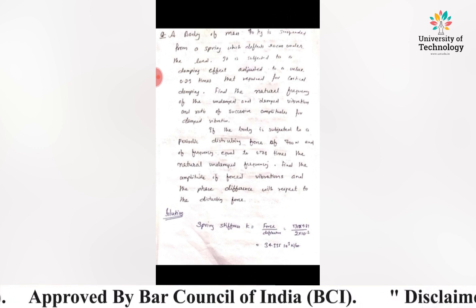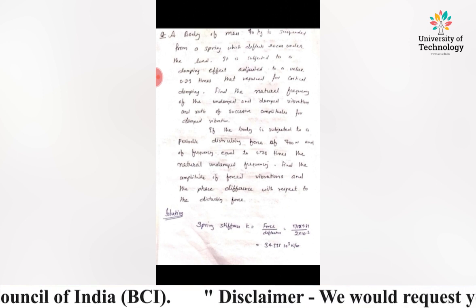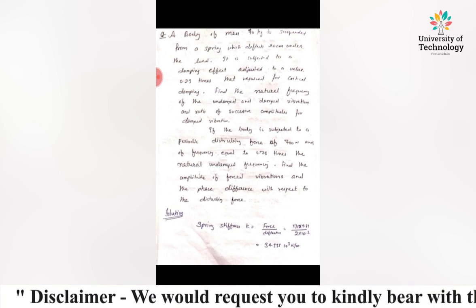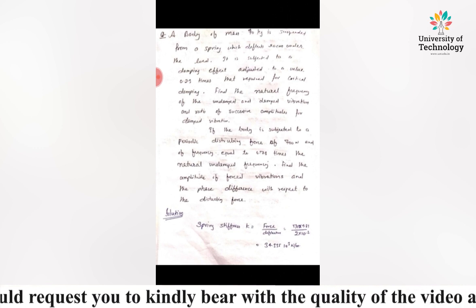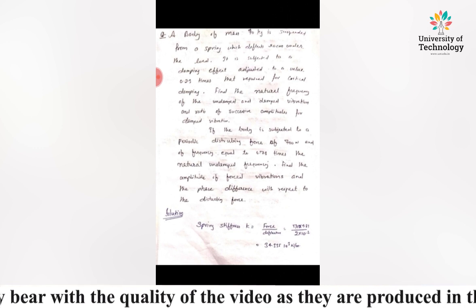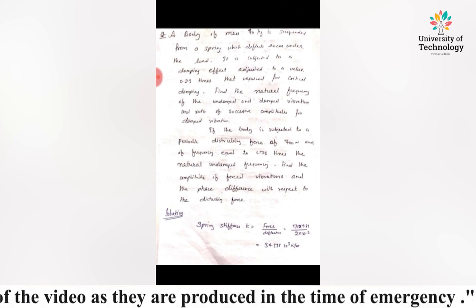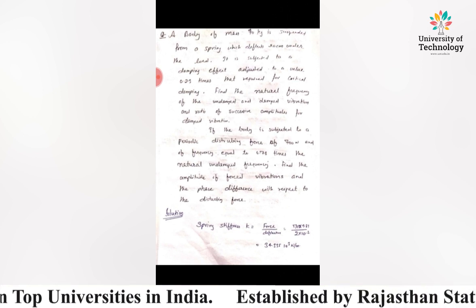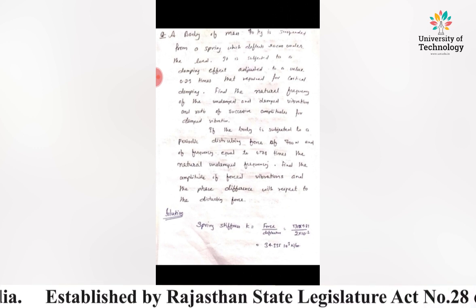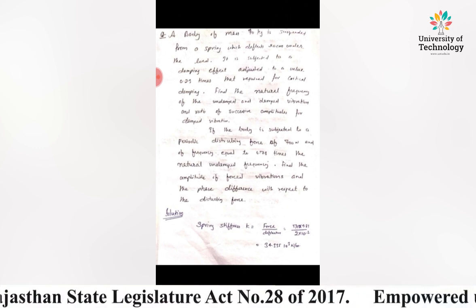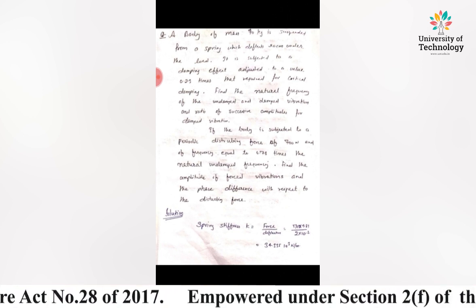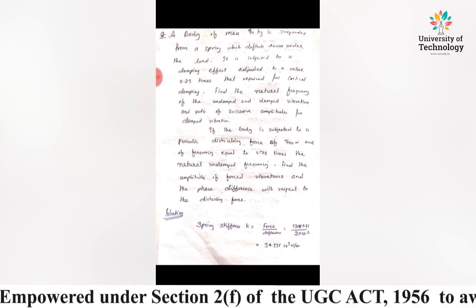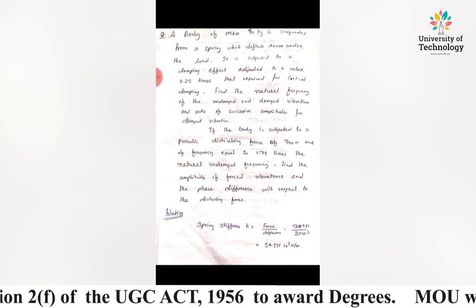It is subjected to a damping effect adjusted to a value of 0.23 times that required for critical damping. Find the natural frequency of the undamped and damped vibration and ratio of successive amplitudes for damped vibration.